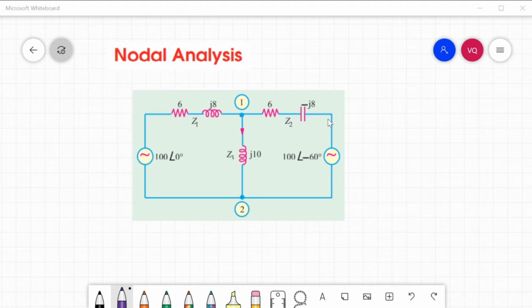DC nodal analysis. The node equation method is based directly on Kirchhoff's current law, unlike the loop current method, or the Maxwell, which is based on Kirchhoff's voltage law. However, like the loop current method, the nodal method also has the advantage that a minimum number of equations need be written to determine the unknown quantities. Moreover, it is particularly suited for networks having many parallel circuits with common ground connected, such as electronic circuits.